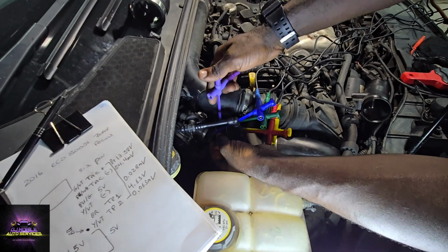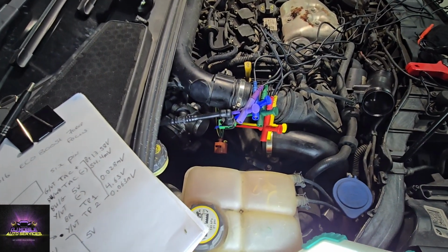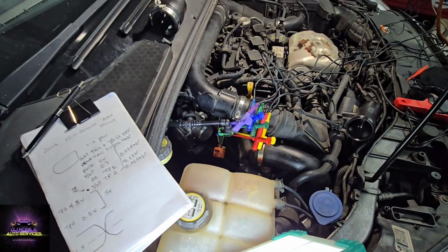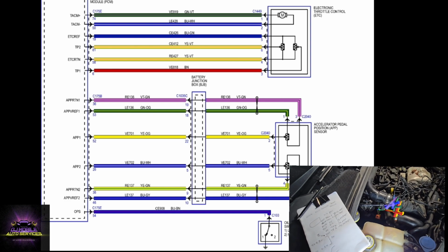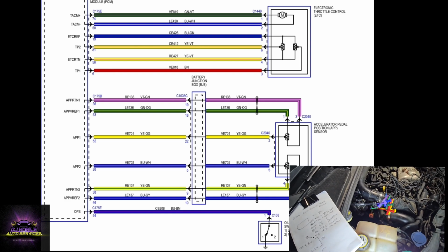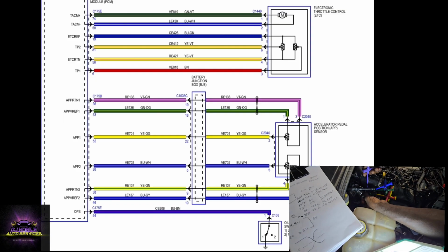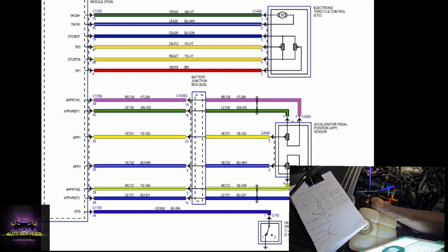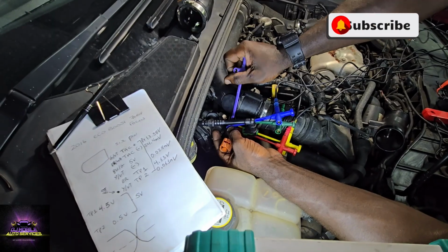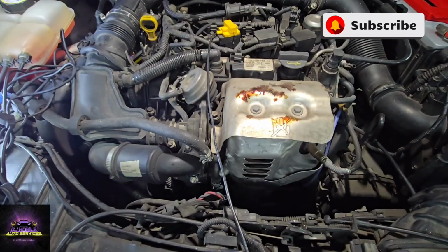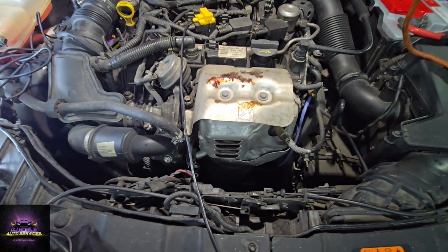It's hard to get the back probes in here, so I'm gonna have to pierce these wires, right? I'm gonna put my amp clamp around one of the wires for the motor. I have the yellow and red, which is basically the power and ground going to this throttle. I have the 5-volt ref, the signal ground, and I have TP1, TP2. So with that now, I got everything covered. I may also put ignition exhaust to monitor what's going on in number 1 cylinder. Yeah, I need to do that because I've seen some crazy things where a coil would take out the ECU and have the throttle acting crazy. So let's get this vehicle to act up so we can get some capture. Let's give it a little RPM.